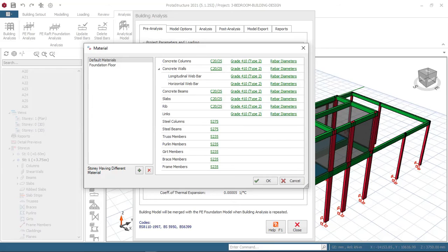So I'll go again on the concrete beam. Now concrete wall, this is not a partition wall. This wall you're seeing here is not a partition wall. So this wall is like a reinforced wall for a lift, or the wall that you can see around the bridge abutment or embankment. So right now we don't use this. Since this wall is not found on this building, there's no need for you to choose anything here. So I'll just move directly.